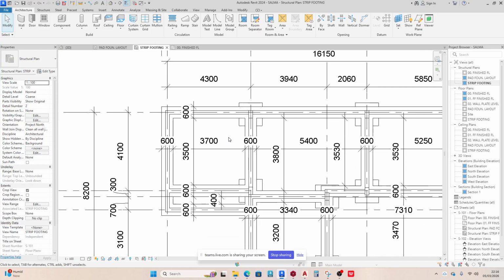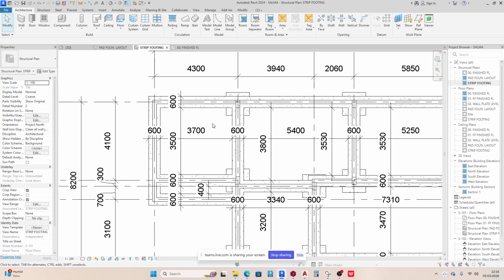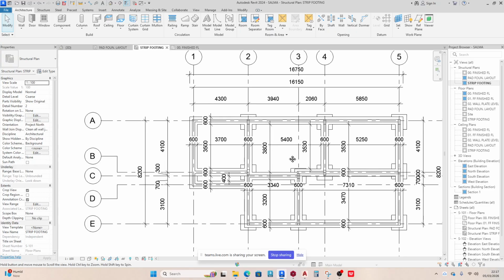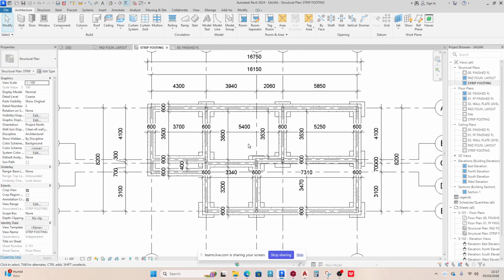If you have a new site, like if it's virgin land, you can engage a geotechnical engineer, and they can perform some geotechnical tests, such as the CBR, the California bearing ratio, and dynamic cone penetration tests or cone penetration tests, and maybe Atterberg limits and plasticity index. All those can determine the bearing capacity for the type of soil on the site that you intend to start building on, and from there you can use that bearing capacity to design.